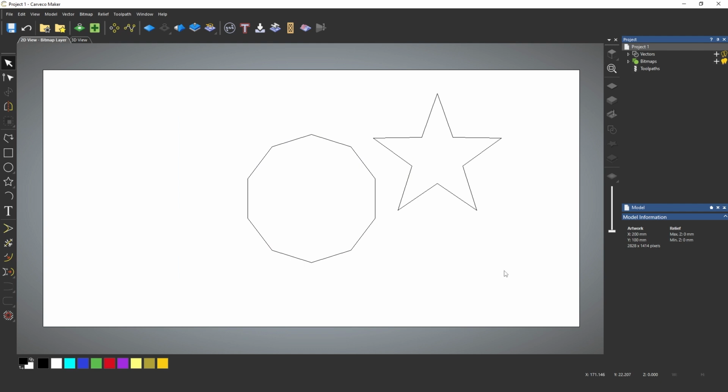Now the difference is if you are dragging from right to left, it will select any object that red rectangle touches. So we can see there it is just touching both objects but not fully covering them, and when I release it, it selects both of them. So that is useful to know. It is often better to select things going from right to left, as that will pick up more objects. With those both selected, I'll hit the delete button.